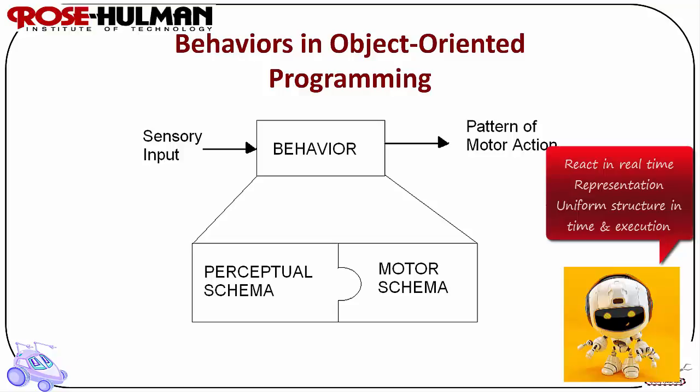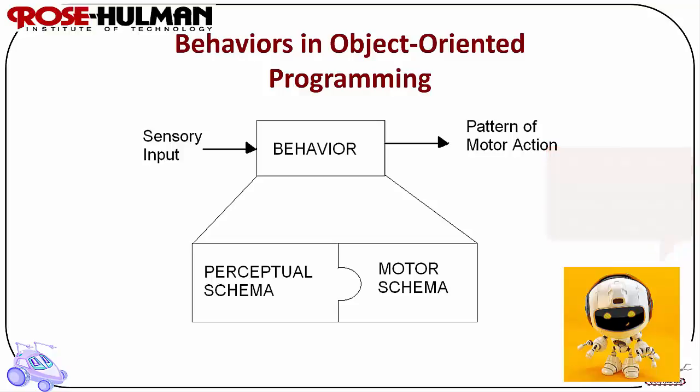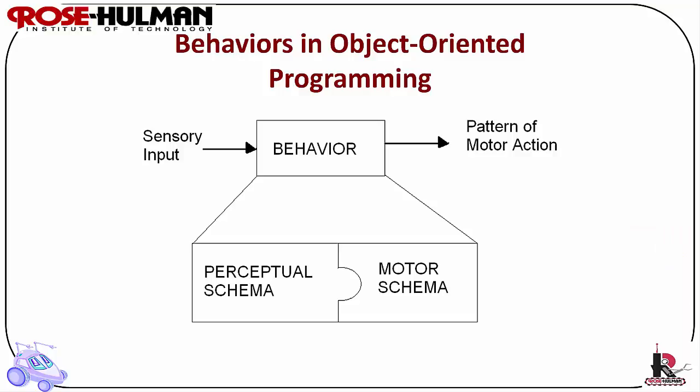It is modular by using a collection of behaviors, and these behaviors are relatively similar in terms of timescale. It is based on a reactive philosophy where behaviors are incrementally added to the system and the behaviors are executed concurrently in parallel. Behaviors are activated in response to internal and or external conditions, and they're more expressive than simple reactive rules. They're more complex and more flexible than reactive rules and can be used in clever ways to program the robot.